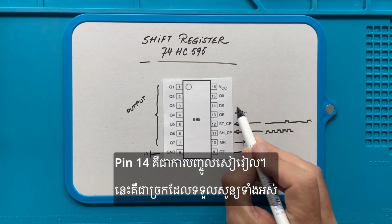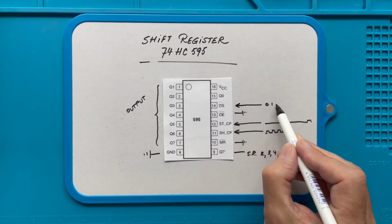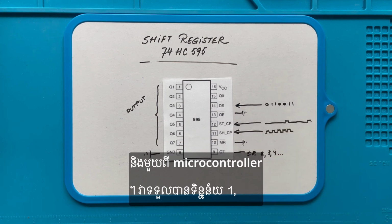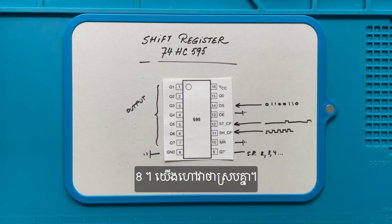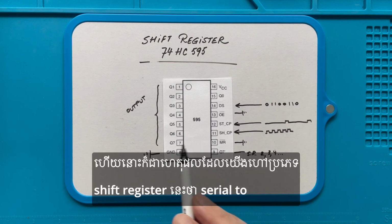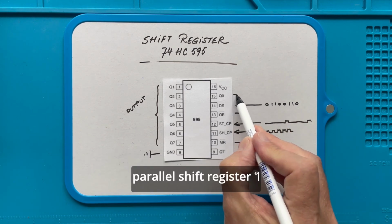Pin 14 is the serial input. This is the gate that receives all the zeros and ones from the microcontroller. It receives the data 1 bit, a 0 or a 1, at a time. We call that serial. The shift register will output that series of zeros and ones in one go to all 8 output pins. We call that parallel. And that is also the reason why we call this type of shift register a serial to parallel shift register.